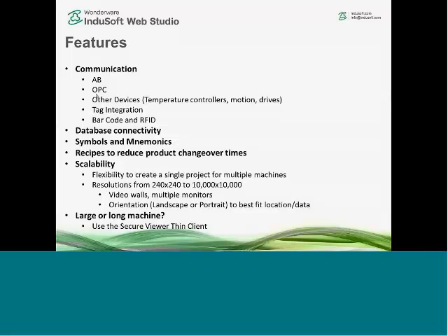And sometimes what I've seen is that even though InduSoft will probably have a driver that you need, there's a chance that there's some other auxiliary equipment that has come in that you need to communicate to, and you can use OPC for that. As I mentioned, there are other devices. It doesn't have to be a PLC. We can talk to temperature controllers, motion control, drives, other types of devices that have some type of communication interface. So don't just think of InduSoft as communicating to only PLCs. Then there's this concept of tag integration.